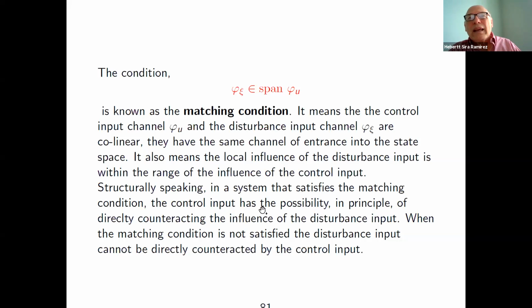In the particular case of the DC motor, it's clear that when you perform a singular perturbation on the electrical equation, the armature current equation, you are left with an algebraic equation relating your control input to the so-called electrical torque and possibly the dissipation in the resistor of the armature circuit. That algebraic equation is devoid of any dynamics.